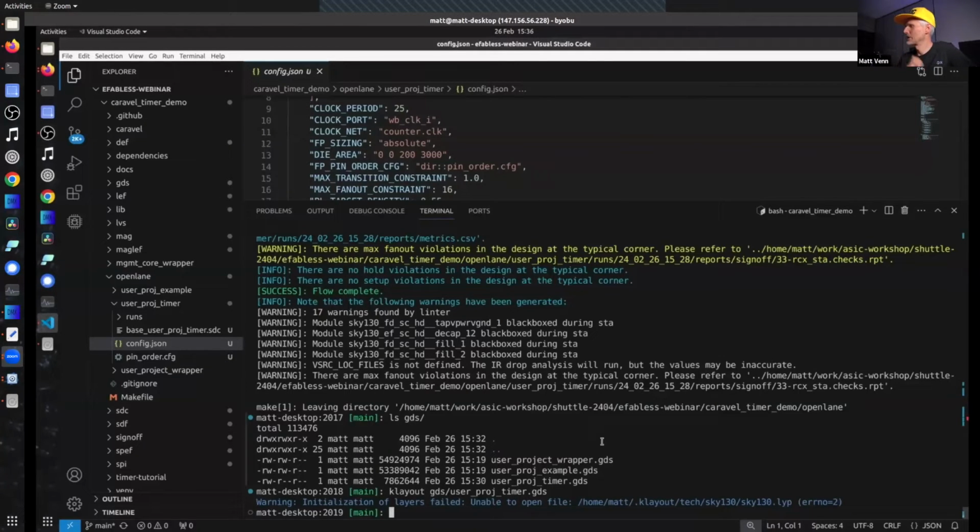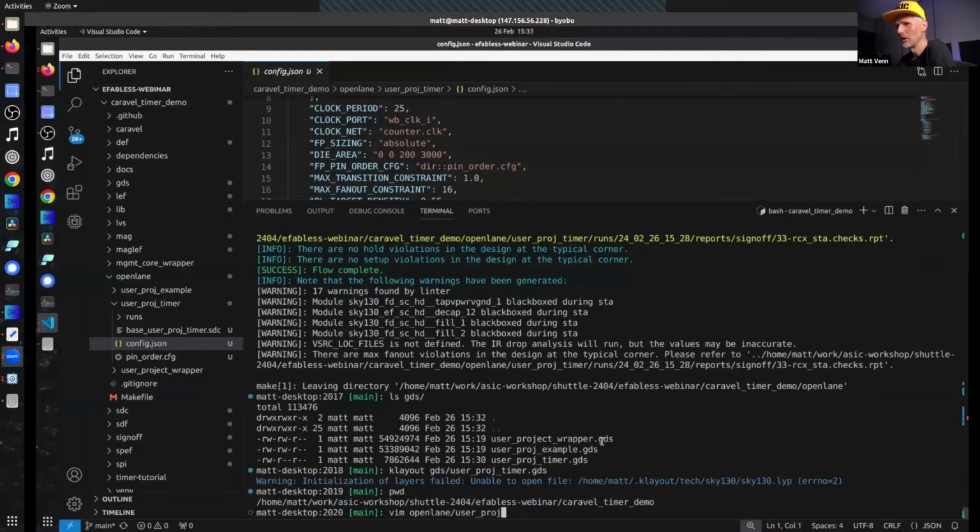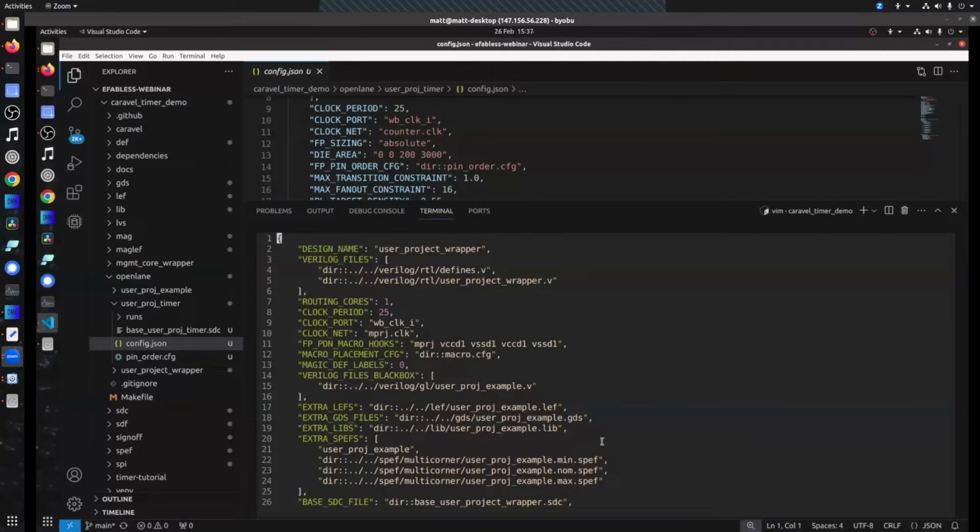Pietro is asking about the schematic view. The schematic view is the Verilog, so I just invite you to check out the Verilog if you're interested in that, because it's not an analog design. It's done with RTL. Well, Yosys does provide a schematic view. Yes. I'm not sure if it's easy to get in OpenLane. No. You just see all the standard cells, which if it's beyond like 10 standard cells, it gets very, very difficult to see what's going on. And Tiny Tapeout is only on Sky130A, so we're not supporting ReRAM at the moment.